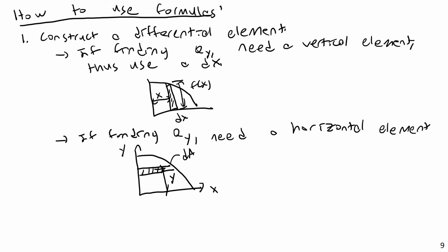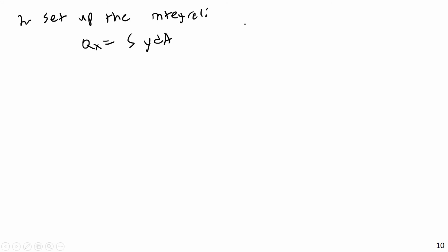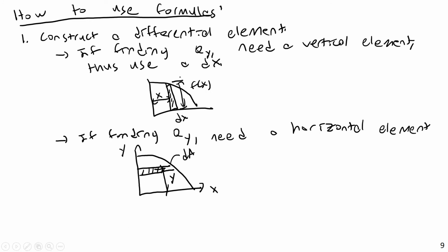Okay, so once you have those, what do you do next? The first thing is we construct a differential element to set up the integral. So you're going to have something like qx is equal to the integral of y dA, and dA, if we're using this diagram here.